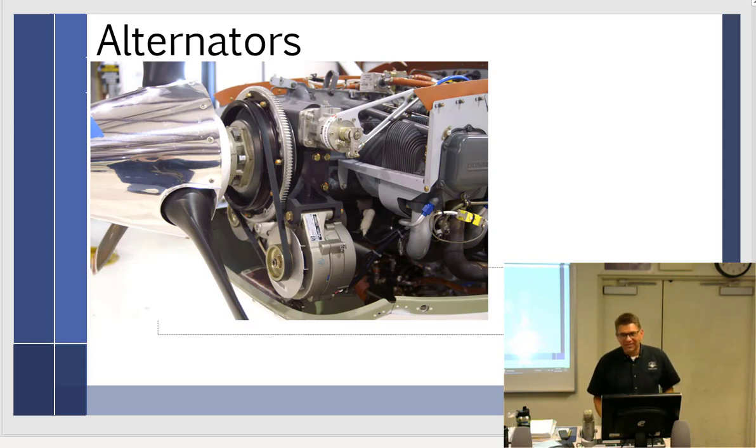Now, in all fairness, it was a 150, right? Yeah. It's not easy to get that alternator out. It shares the same gasket with the tach drive, so you have to cut that, split it, put that in, and usually you have to take the magnetos out to get to all the hardware because it's buried. So you have to pull both mags and the generator, then retime it, put it back in, then retime it, put it together. So it's labor. You're paying a lot in labor.